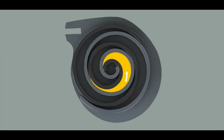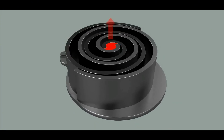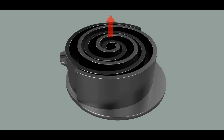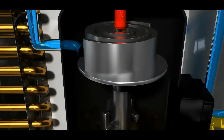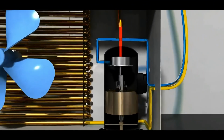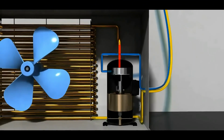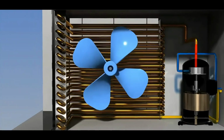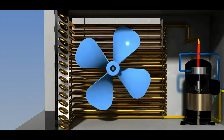As there is less space now, gas becomes more compressed, and is discharged from the middle of the scroll in a compressed state. The reason for using such a type of compressor is the efficiency of space utilization. This type of compressor allows the machinery to become smaller in size and reduces noise as well as vibration. Compressed air is then sent to a condenser to be pressed into liquid.